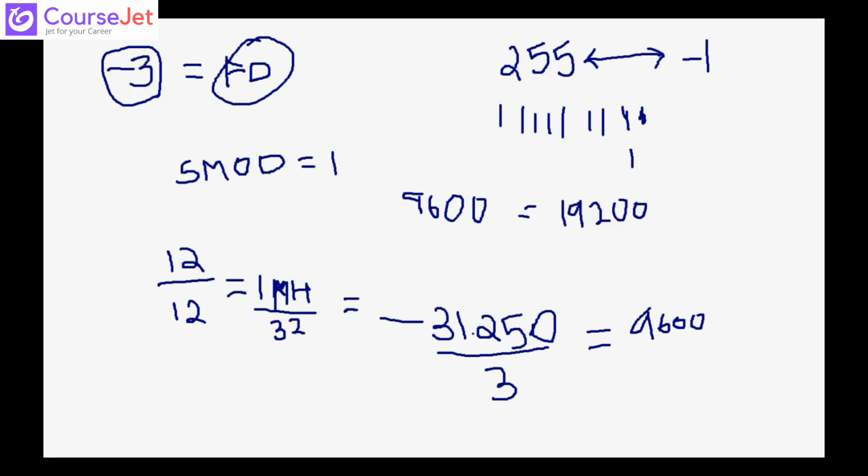If you see in the serial channel, the mode is 8-bit mode, the SCON register value, and the SBUF register value is loaded with 65, which is nothing but 41 in hexadecimal. TB8 and RB8 are not loaded. Receive enable is ticked, and the baud rate is 9600. Is it clear? If so, I'll stop it and go to Proteus.